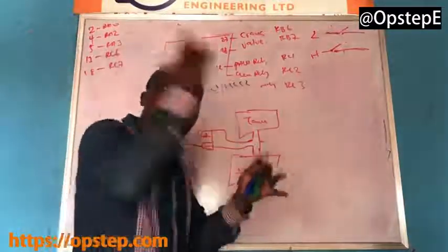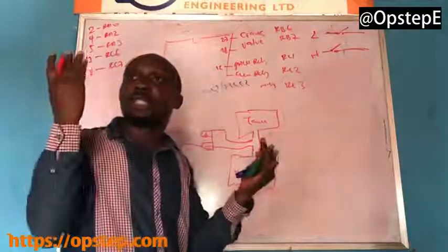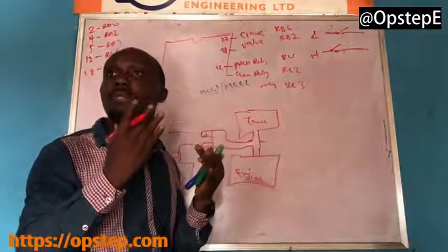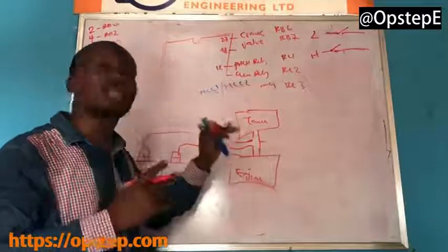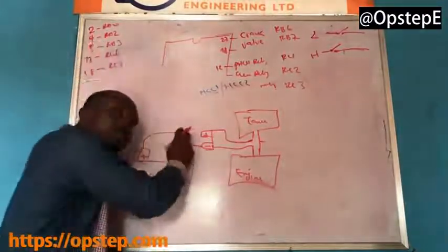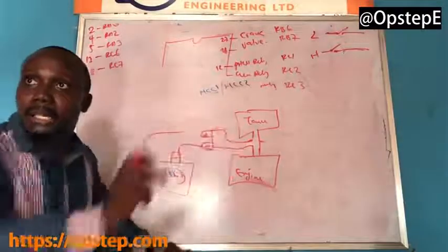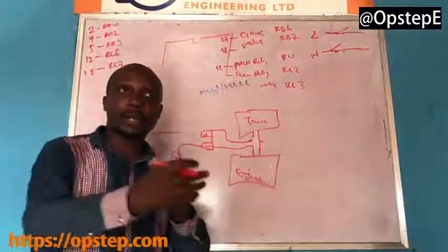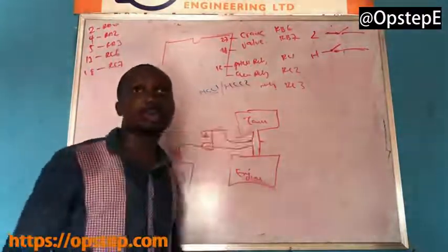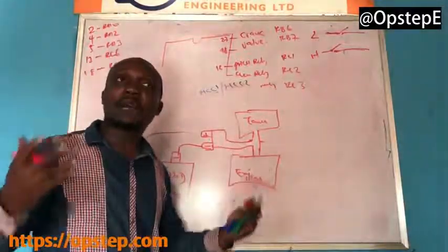The moment you withdraw that voltage, are you with me? The relay loses coil voltage and then the valve is off again. So fuel cannot flow. So before you can actually even start the generator, you need to therefore turn on the valve. So it is when the valve comes on that you can then go and crank. It's like starting your petrol generator without it; even if it starts temporarily, after a while it will go off.